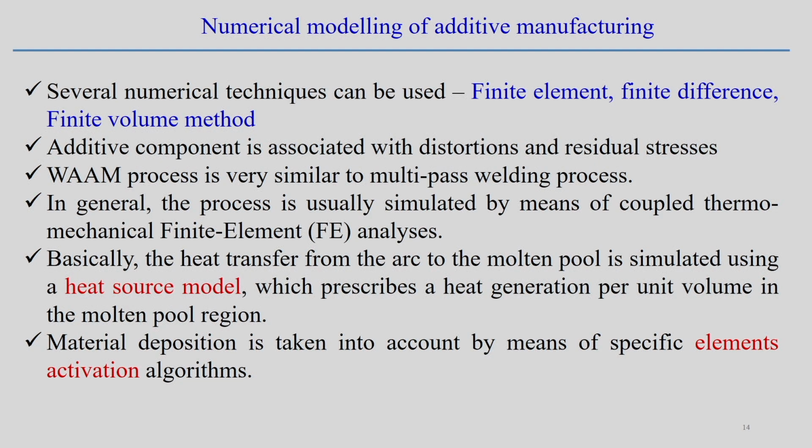And in general, when you look into the model development for the additive manufacturing process, the element activation and deactivation technique is very important, because it is a kind of progressive model, where you are progressively adding material to the domain. So we keep on adding material to the domain, which is a better way in the finite element approach. We keep on activating the elements along with the deposition of the material, and this activation technique has to be understood to develop the additive manufacturing process model.